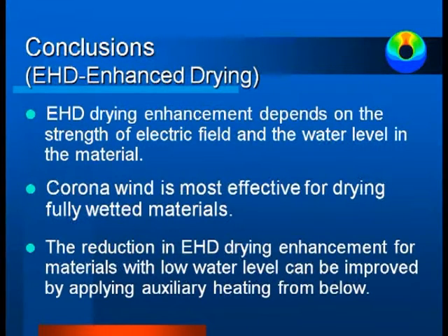Corona wind is particularly good for fully wetted material. For partially wetted material, it may require an auxiliary heater to get the moisture up to the surface. That is the conclusion we can make from this study.